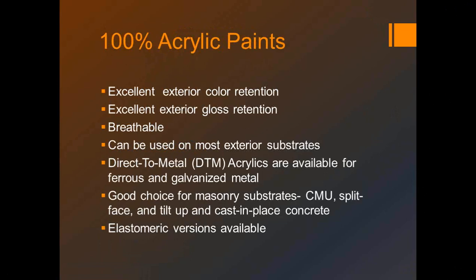Now, would you use an acrylic paint on galvanized metal, say gutters and downspouts? Most definitely. Galvanized is one of those kind of things. There are a few solvent-based finishes, normally cementitious solvent-based primers that you can use on galvanized, but a safe rule of thumb is to use latex or use acrylic paint on galvanized.